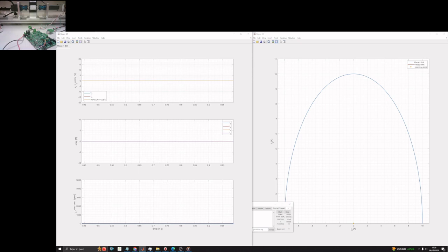And here you can see the speed omega and the reference speed asked by the user. And in the IDIQ frame, you're going to see the different limitations of the system, and especially current limitation and voltage limitation, and of course the operating point computed by the flux weakening program.